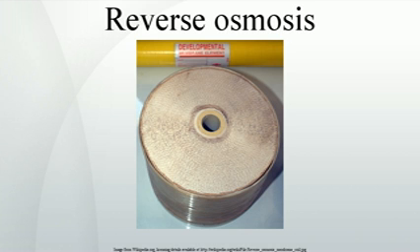Brackish water reverse osmosis refers to desalination of water with a lower salt content than seawater, usually from river estuaries or saline wells. The process is substantially the same as seawater reverse osmosis, but requires lower pressures and therefore less energy. Up to 80% of the feed water input can be recovered as fresh water, depending on feed salinity. The Ashkelon seawater reverse osmosis desalination plant in Israel is the largest in the world. The project was developed as a build-operate-transfer by a consortium of 3 international companies, Veolia Water, IDE Technologies, and Elran.